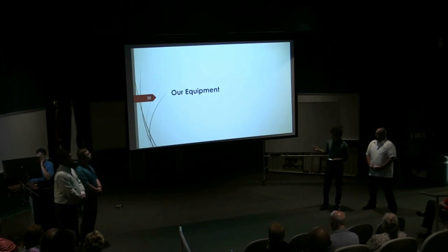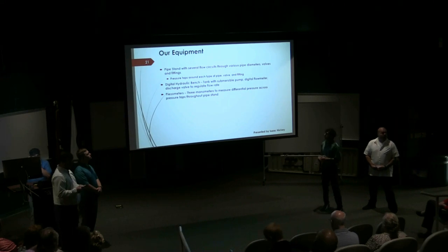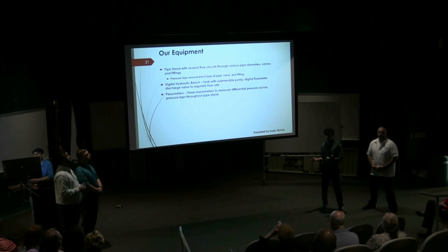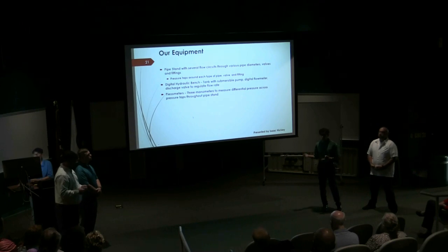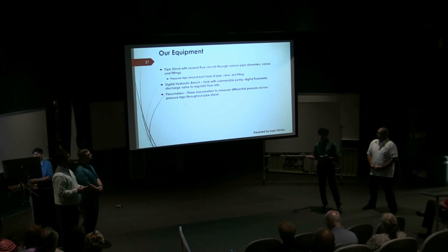Now we're going to talk about our equipment. We have a pipe stand that has pressure capture on each type of pipe, valve, and fitting, a digital hydraulic bench, basically a tank with a sub pump that pumps fluid at a constant rate throughout our system. We have a piezometer, which is basically 3 manometers, measuring inches of water column on the inlet and outlet side.